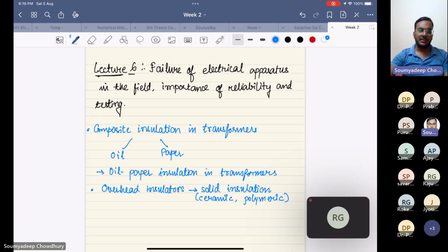The first advantage is the reduction in weight. Almost 50 to 60 to 70% there is a reduction in the weight. So suppose the technician or the lineman who goes on repairing these insulators, who goes on monitoring these insulators, has to carry those insulators before installing or commissioning them on the actual power line. So a lineman or a technician will obviously prefer the lower weight insulators. So that is one of the biggest advantages of polymeric insulators.